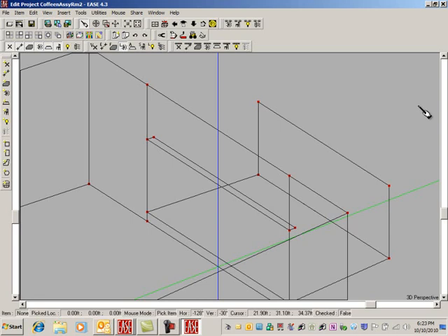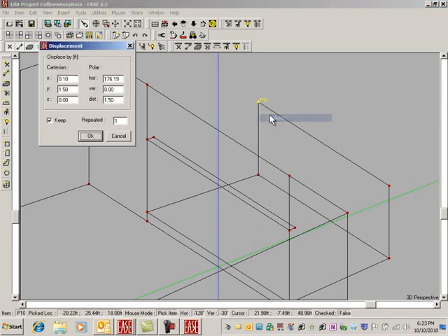So it'd be 5.5. Now our horizontal angle isn't this any longer because we're going in the opposite direction. This is 0 degrees, so I think it's minus 4 degrees. We'll find out. I'm going to make it minus 4 and see what happens. Say OK. And there's that point. If we say OK, and then if we look at a plan view of this, like that, oh boy, it's right on that line. That's our floor line. Looks like we did it exactly right.